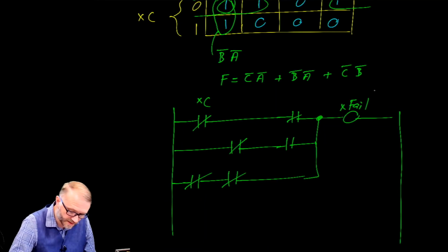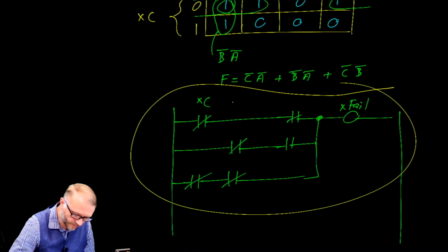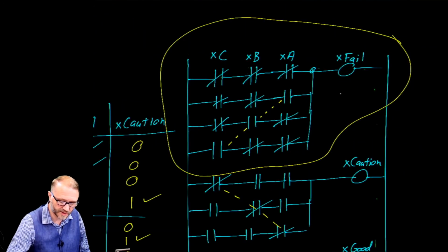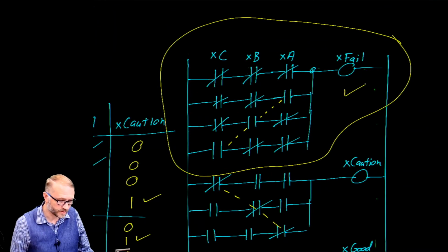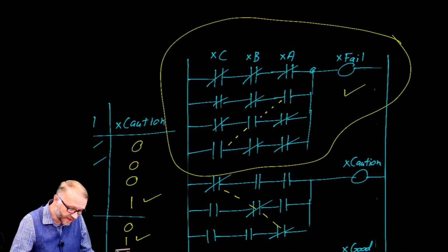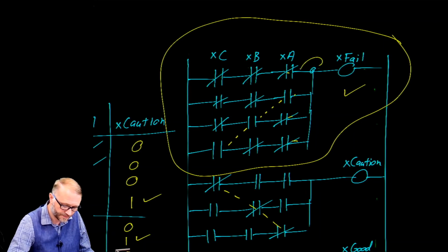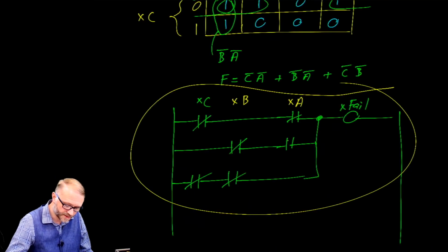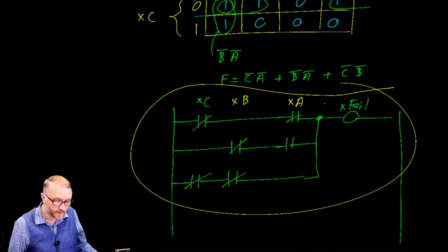I will tell you that this circuit, where this is the Boolean B column and this is the Boolean A column, is 100% functionally equivalent to this circuit. They will do the exact same thing. In our first circuit, we had 1, 2, 3, 4 three-input AND gates, and this is an OR gate. And here we had 1, 2, 3, that's one less, and there are only two-input AND gates and a three-input OR gate. So it is considerably simpler.